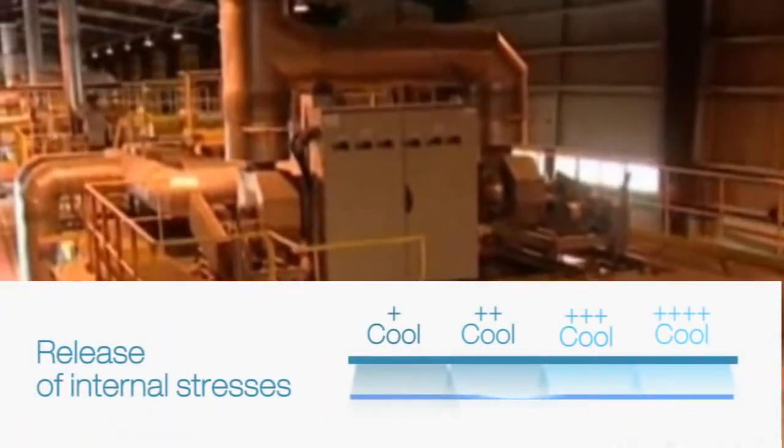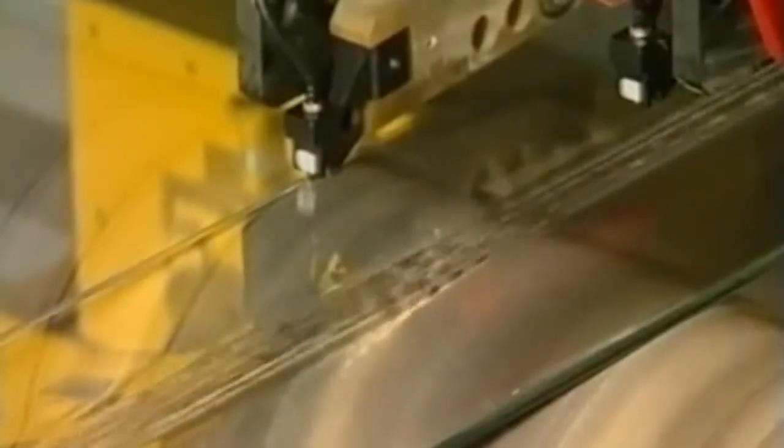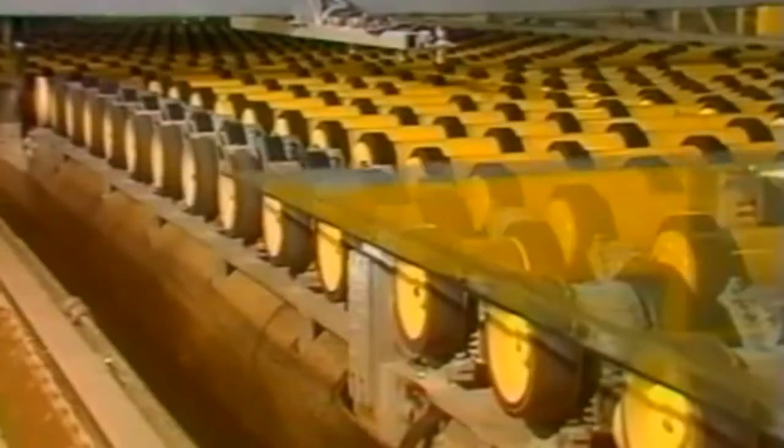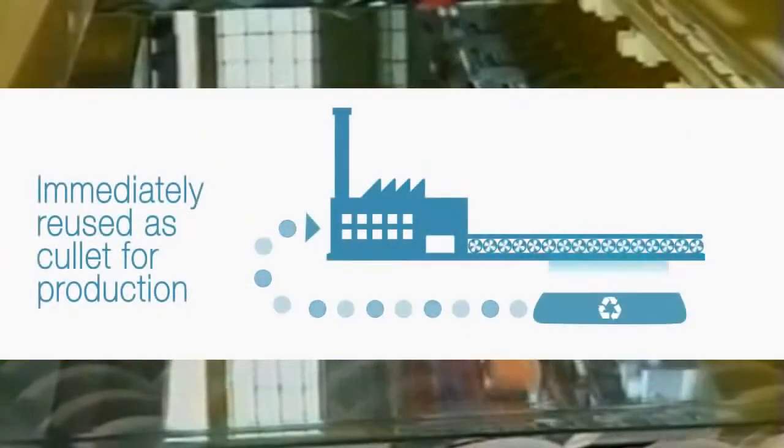The glass ribbon needs to be gradually cooled down to ensure the release of internal stresses. Cooled down too quickly, glass would break. As the glass is cooled down and solidified, the glass ribbon is electronically inspected to evacuate defects. Edges on both sides of the ribbon are cut. These edges and any glass area not fulfilling the high standard of quality required go back into the furnace for recycling.